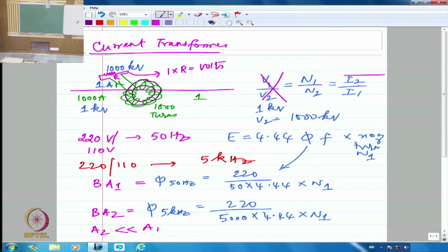That's one reason why if you look at the electronic systems, generators, all those things in aircrafts, they will all be operating at 400 hertz generally. They will not be operating at 50 hertz. We are not transmitting it anywhere. It is within the aircraft itself. So we may have generator, we may have electronic systems.